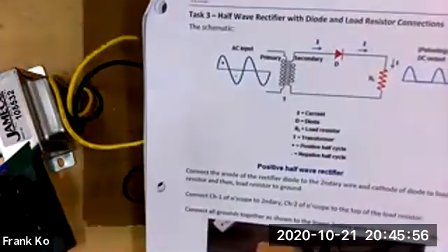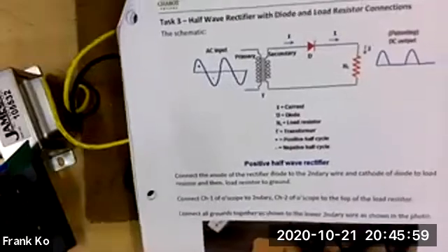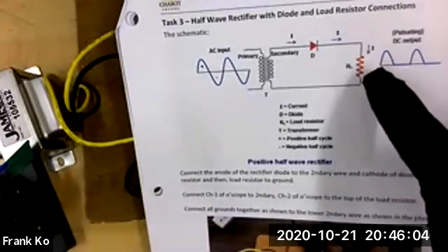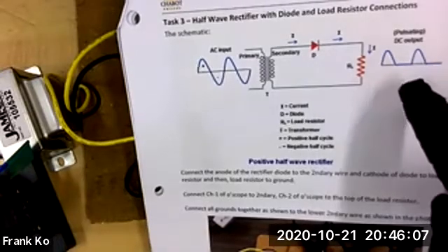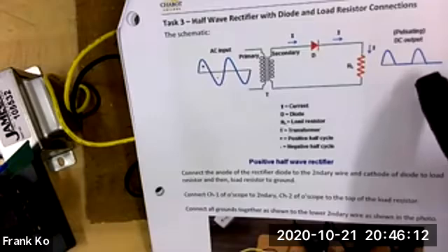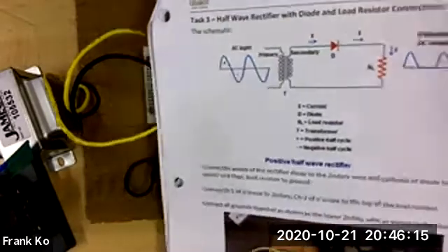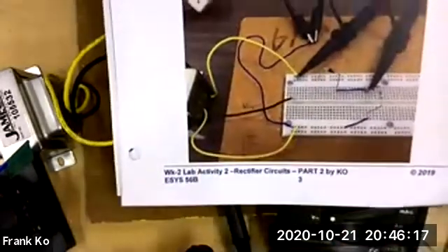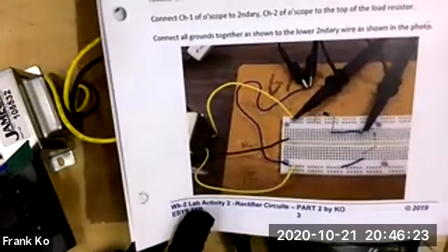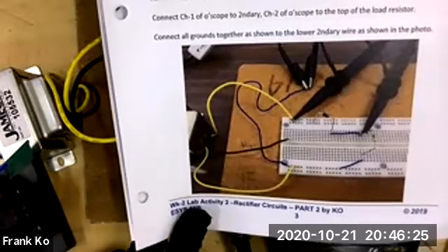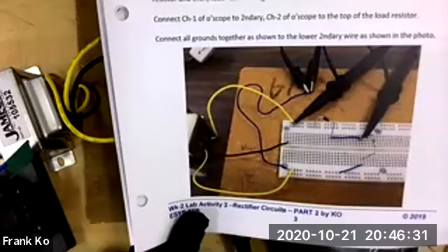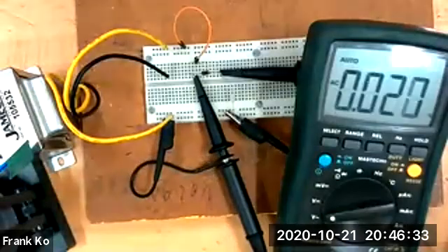So then, over here, we take a look at this next thing. Did we hook up a diode after the secondary, before the 1K ohm load, and were we able to demonstrate AC on one side and positive pulsating DC on the other side? Yes? Okay, and then if we take a look at the illustration shown on the bottom of this page, that's in fact what you had done, all right? Slightly different colors on your secondary wires. Instead of yellow, as it is on mine, they happen to be white on yours, but we have effectively the same thing. Flip the page.